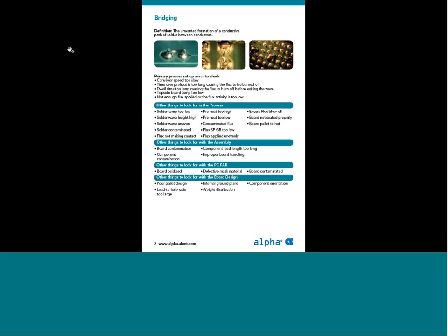How old is the board? How is it stored? How about the mask material? Is it properly cured? Does it have bubbles? Does your board have contamination? Has it been sitting out and has perhaps oils from the air, things like that?